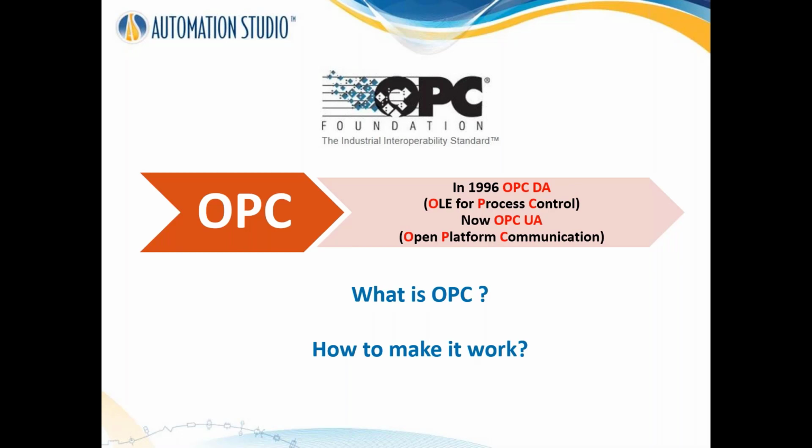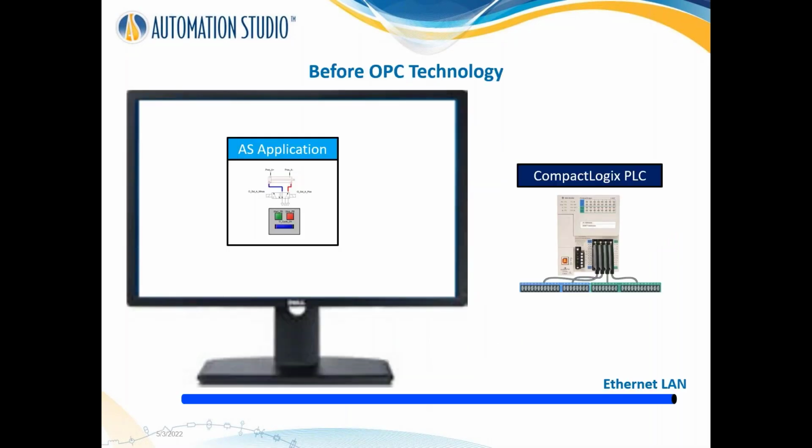I went over what OPC is, and just to show you very briefly, before OPC technology we had an application, and to make the application communicate with an external PLC, we had to write what is called a communication driver. The communication driver used the manufacturer's catalogs for protocols and details, and we had to write a very specific program to associate with the application to communicate with this specific type of controller. Whenever we had to change the controller on this side, we had to start over again and write another communication driver over here. So that was basically the situation before OPC.